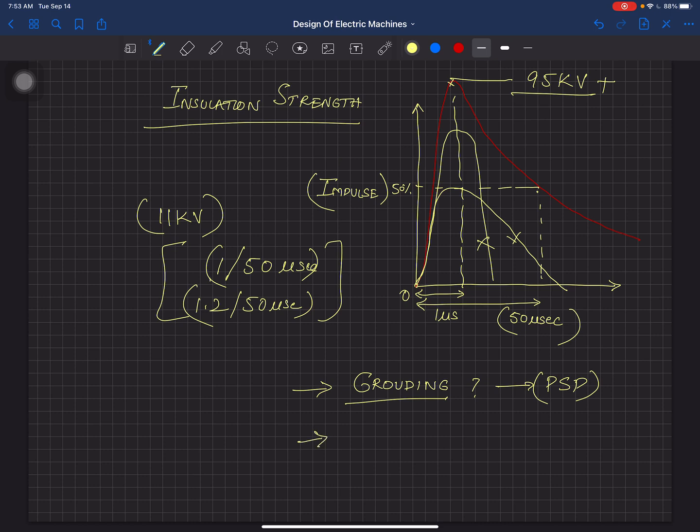And the second thing which I want to ask you is the percentage impedance, how that is calculated, and how per units are calculated. This is very much important, because when you are designing a transformer, you have to convert them into your percentage impedance or per unit values. And I guess the third question, which is very much important, we have discussed a little bit also, is how frequency and voltage are linked for any transformer design. So almost like there are just 2 or 3 questions I have left over there. I will share that Word file with you also. So these are some questions.